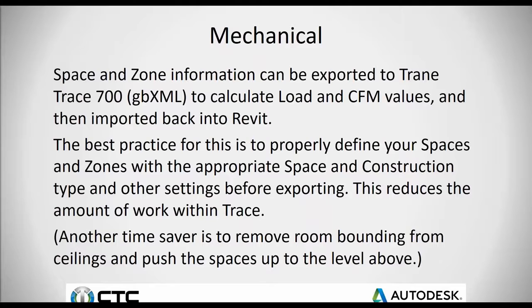So for me, the best practice I've found is to define our spaces and zones as accurately as possible, and also I push my spaces, I push that volume all the way up to the level above and make all of my ceilings non-room bounding.